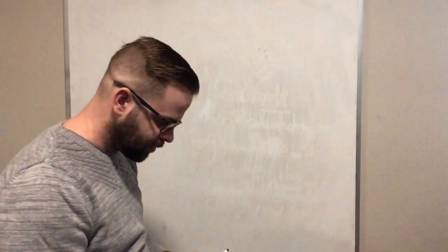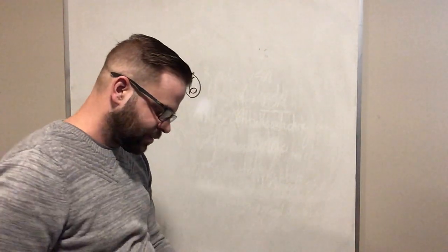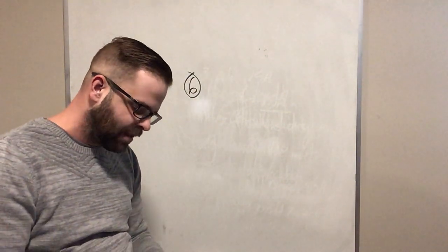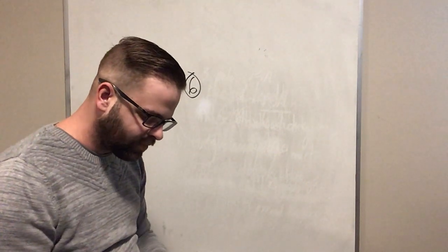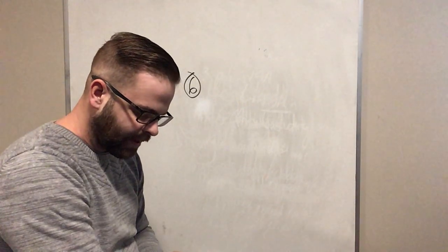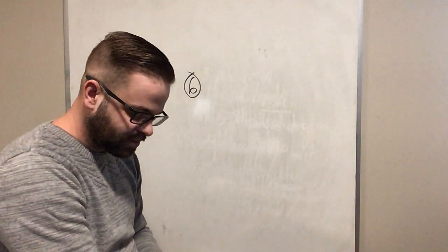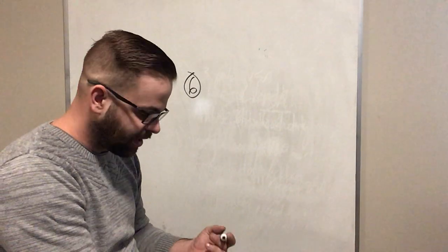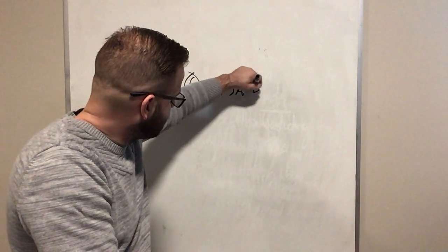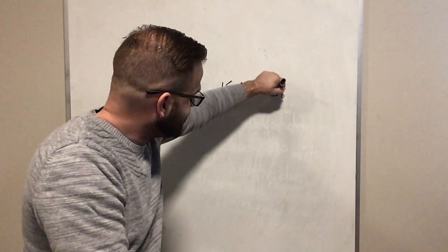And now we're going to move on to 6. So 6 says, where a fuse switch, and this is very similar to the one before it, where a fuse switch or circuit breaker is marked for continuous operation at 80% of the ampere rating of its overcurrent device. So this is basically every situation that you would see day to day. So that would be, we've got a 15 amp breaker. It's rated at 80% of its operation at continuous duty, which would be 12 amps.